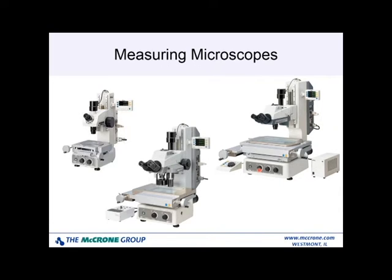Measuring microscopes work in a very similar fashion. They have a measuring stage. They have an area where you have either 1 objective or 2 objectives or more. You can mount a camera on the top of the microscope, but instead of a screen, you have eyepieces, either a single eyepiece, as in this instrument, or dual eyepieces, as in this instrument. You can get up to 1000x magnification. You may have a turret with multiple objectives, and of course you can mount a camera on these as well.